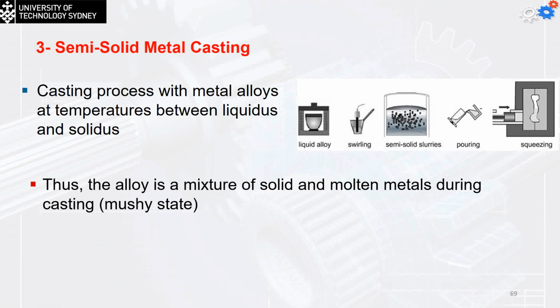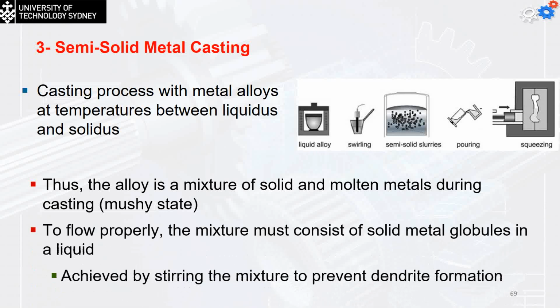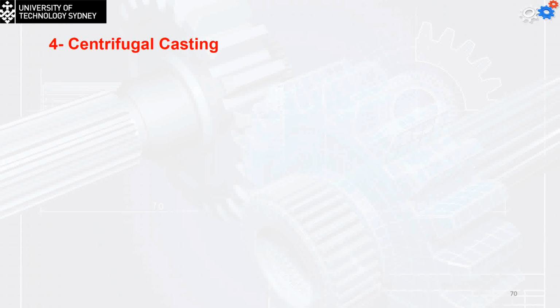The centrifugal casting, as we mentioned once again, is the process used to make the metal pipes, the big size ones. And in this case, the mold is going to be a cylindrical shape, rotating on rollers. When you pour the metal, due to the centrifugal force, it is going to be attached to the wall, building the layers, solidify, and we're going to have the desired shape.